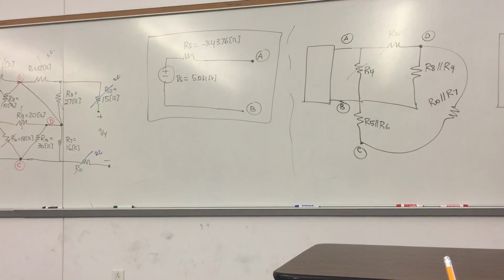And I have R8 in parallel with R9 in parallel with the series combination of R5 in parallel with R6. The parentheses are extremely important during that procedure. R10, and then in parallel with R7. Okay, that's it.